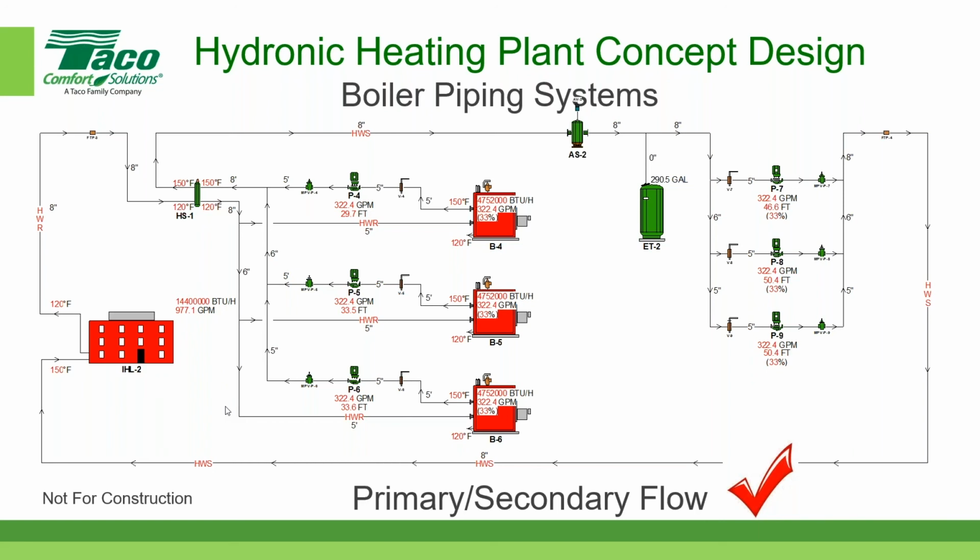So, let's say you had a fan coil system, and each fan coil had an entering water temperature of 150 and a return water of 120 at its design capacity. Well, if I supplied that terminal unit with a higher supply water temperature with a lower delta T, then I would not need as much surface area, and so the terminal units would be less expensive. So it's always a trade-off.